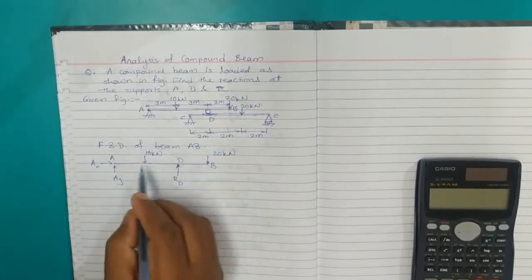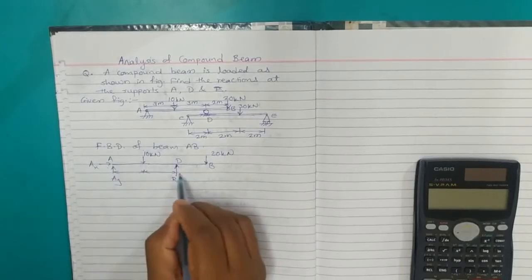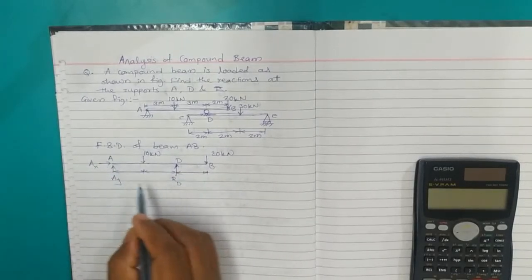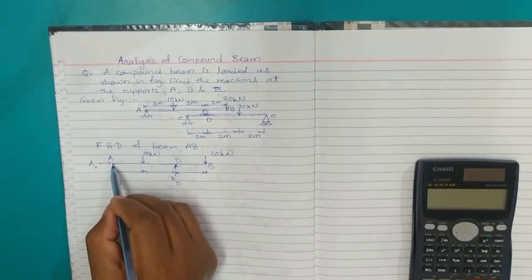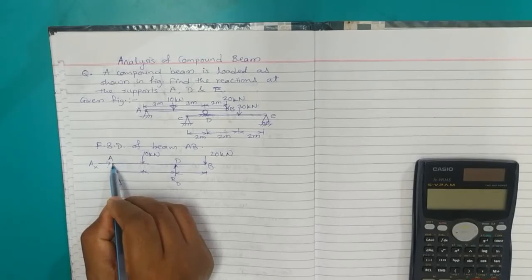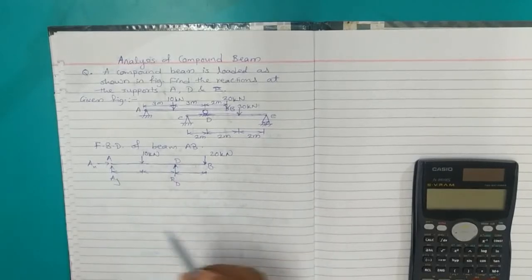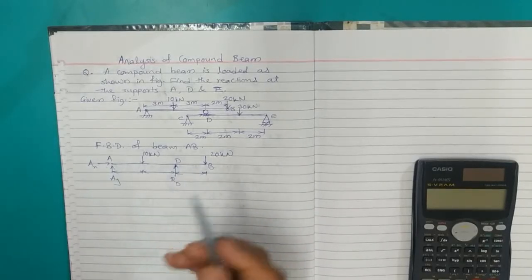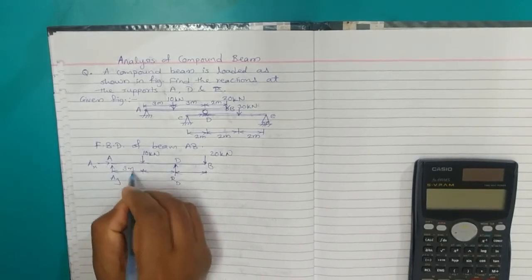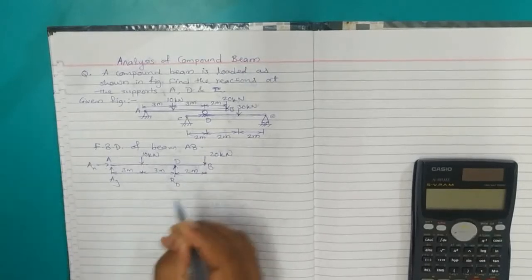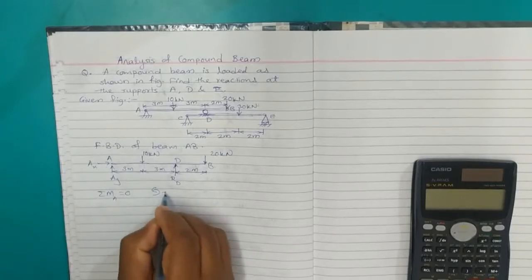This is the point D, and all the dimensions are known to us. So with the help of these dimensions, we are going to solve the unknowns Ax, Ay and RD. We know the procedure. As far as possible, wherever there is a hinge, we apply the condition of moment about the hinge point so that the remaining unknown gets solved. And then we use the summation Fx equals 0 and summation Fy equals 0 conditions for solving Ax and Ay. Let's write down these dimensions: 3 meter, 3 meter and 2 meter. Let's apply summation MA equals 0, taking anti-clockwise positive.